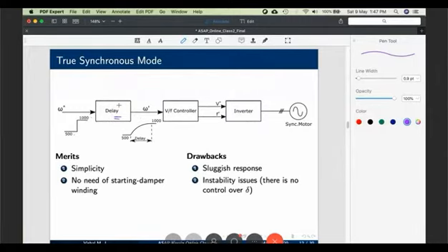It could be a first order delay or second order delay or third order, depending on the factor of safety you want. You can make a delay block. What the delay block does is what I have shown, from 500 to 1000, not in a stepped manner, but in a slowly, gradually changing manner. So from omega star, which is your frequency command, you get your omega prime once it goes through the delay. From that, we can calculate the value of frequency.